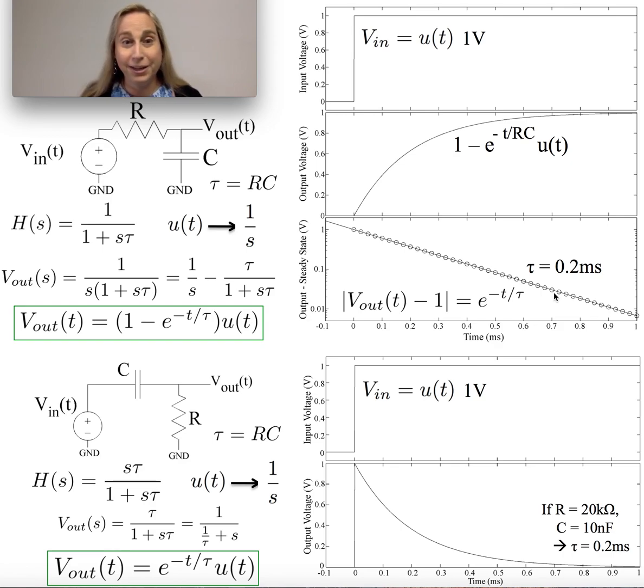And I'm sure many of you will get an experience to do this, either with your own data or with data that people might hand you, and you can actually go, oh, this is a good way to get the time constant. It's also a good way to tell where a system is being linear, because a linear system would always have these kinds of step dynamics. Where it deviates from these step dynamics, what you realize is it's not so linear. So the whole point here was to talk through how we look at these two circuits, which are basically linear first order circuits, and what is the time behavior that I might imagine out of these kinds of structures.